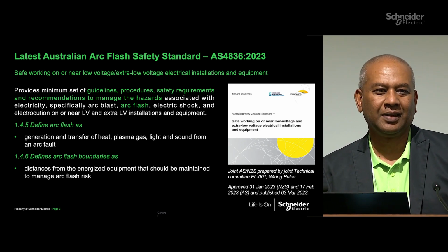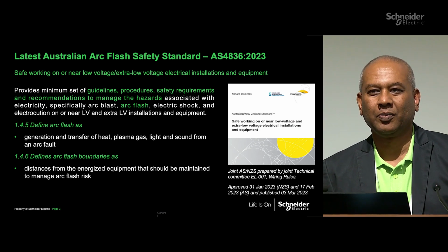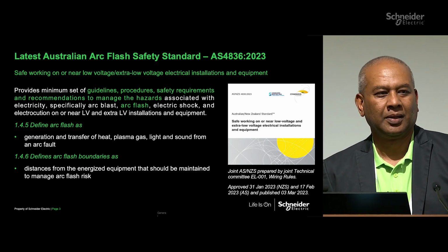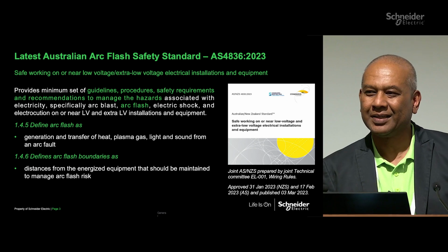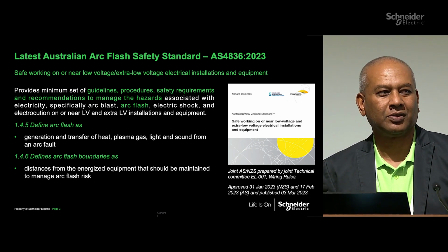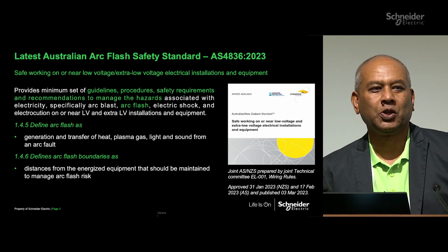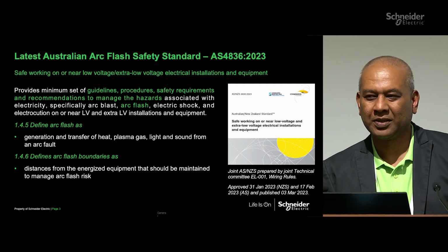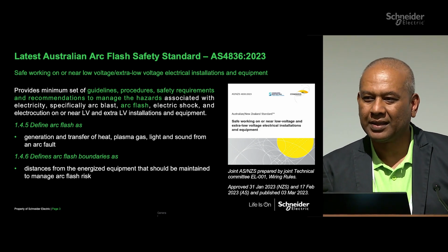So if you don't have this standard and you are thinking about arc flash or working with arc flash at your sites, then my advice is get this standard, because this is probably the only standard you need to make things happen as far as arc flash is concerned on your facilities. You don't really need NFPA 70E, because whatever is in there is embedded in this standard now. And you don't need IEEE 1584 as well, because that is more a calculation standard. It is useful for people who are calculating the arc flash hazard categories and doing all that. And we have software tools these days that are doing those calculations.